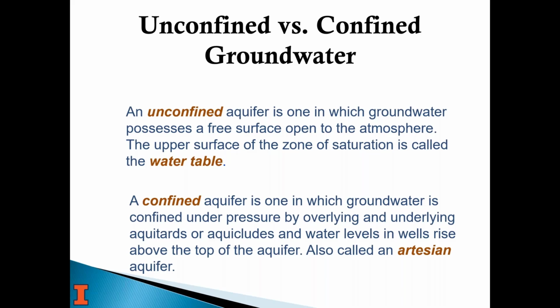At the top of the aquifer there may be an aquitard that totally confines it and keeps it under pressure. If I poke a hole in it with a straw, all of a sudden the water can come up the straw. Again, it's like squeezing a juice box. If you push hard enough, it's going to squirt out, and that's what a flowing artesian well is. So artesian just means under pressure. It doesn't mean the water's flowing out the top. Flowing artesian means it is actually flowing out the top of the well.